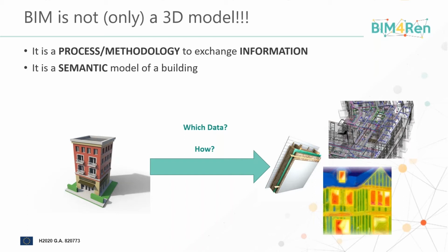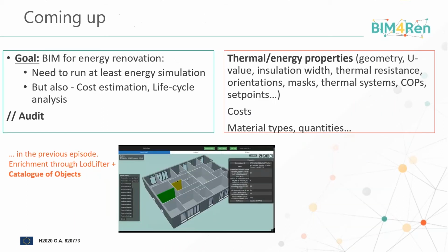So today we're going to speak about energy renovations. Of course, in an energy-related project, what we are interested in is collecting the information related to the energy efficiency of the building, and all the data that are valuable to run energy simulation, like part of the geometry, but also the U value, insulation layers, thermal resistance, set points, and so on.